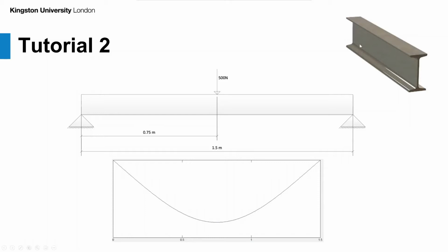So we're going to consider that as a normal line, then add the force section later at the FEA level, and bring in the conditions, which are two fixtures on the sides and exactly in the middle a 500 newton force applied. As we can predict, there should be bending in the middle, and we're going to see how the CAE results confirm that. So let's open up the Siemens NX software and see how it performs.